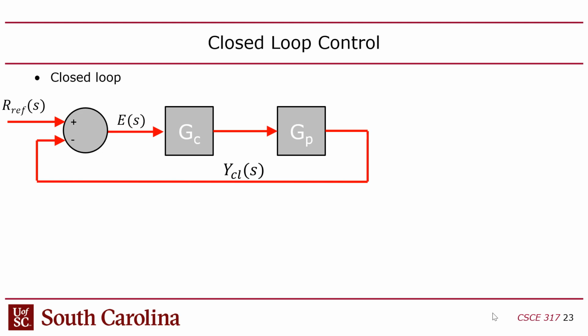But this y is where the coin is. This is not a transfer function. This is a signal, right? It's a time series signal or a frequency domain signal. Likewise, the error is just a signal. It's an S-domain function. So you've got two transfer functions in here, but you've got them mixed in with these variables, basically. And then you've got ref. This is your set point, and your set point you can change. It's dynamic. Like if I have a robot, I may want to continuously change the position of the coin, and he has to figure out how much force to apply, right?